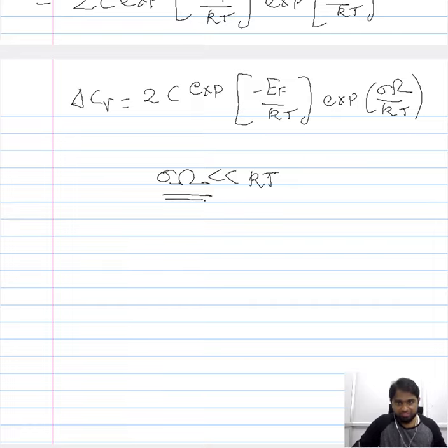the combination of the stress and the molar volume, when you compare it to the Boltzmann constant and the temperature, which is nothing but the thermal energy, or the activation rather, the thermal energy that is introduced by the temperature, then its relation looks something like this, meaning the combination of stress and the molar volume is significantly less than that of the combination of Boltzmann constant and temperature.